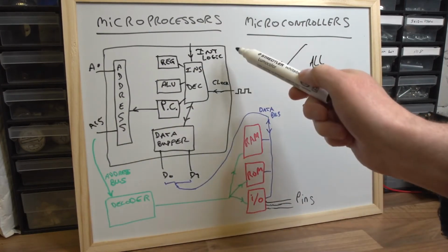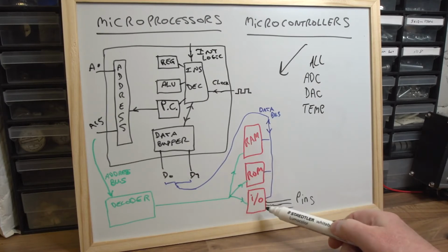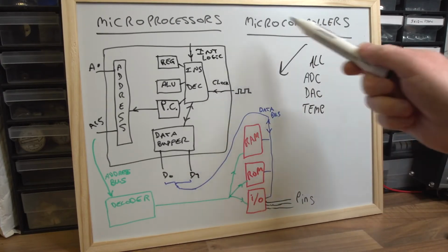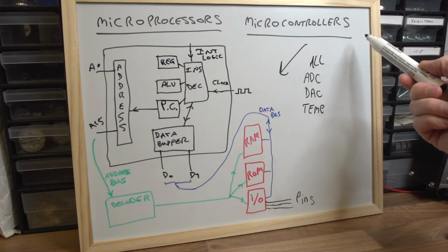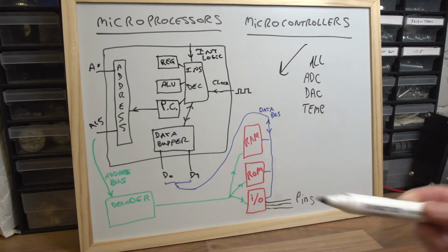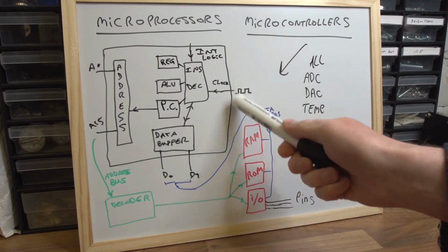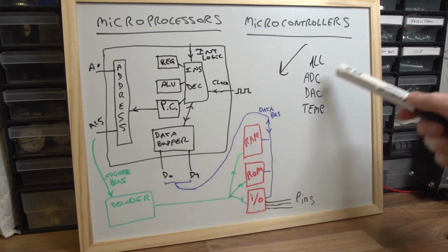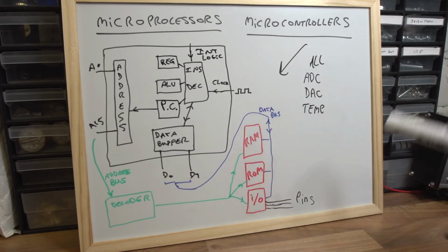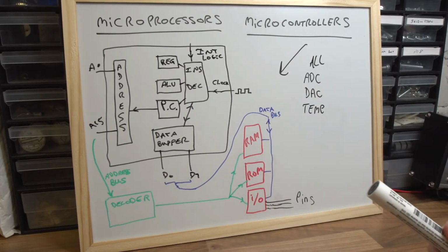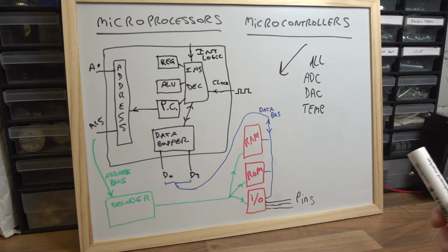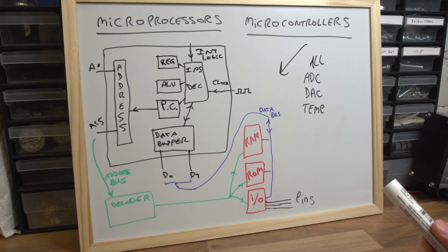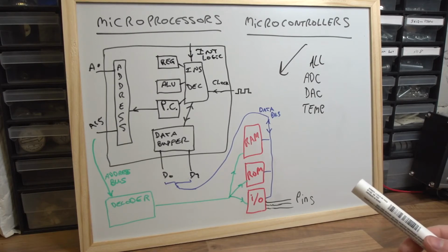You've got a microprocessor, decoder, RAM, ROM, I/O. And the clock circuit as well is usually internal on a microcontroller, can be external. You can have it connected to a crystal, but they also have a lot of internal oscillators as well, so you don't even need an external crystal. You can actually just use the internal oscillator, and all that's built in. And these extra functions and some other stuff as well. Some of them have more built-in, better mathematical functions, like maths processors built in, like MPUs and all sorts of things. So, you know, it's just getting more and more advanced as time goes by.